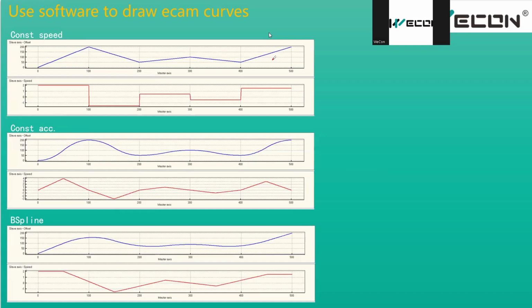If one load, for example, from 0 angle to 360 angle is 1 cycle, then you can set the master length as 360 angle. For example, if your master rotates one load and needs 2000 pulses, then you can set the master length as 2000.